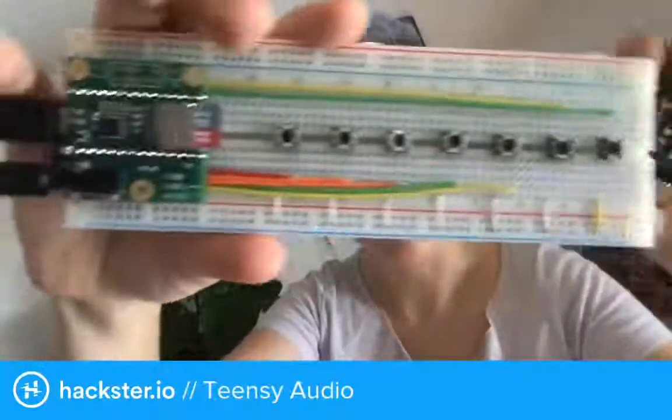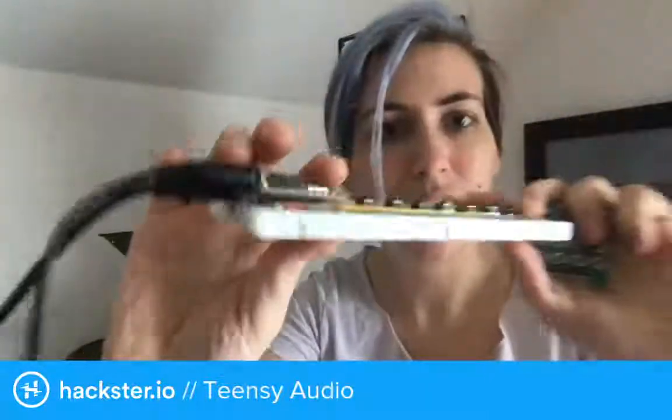Yeah, so here's the audio tutorial kit. You can see there's a Teensy underneath. I did a kind of janky thing where I accidentally soldered the Teensy too close to the board underneath because I only had one size of headers, and I was worried about heat problems, but that hasn't been an issue so far. The main problem is that I can no longer reach the reset button, which is back here. It's literally like 0.5 millimeter below the audio board, and so I had to instead solder on a new reset button, but that works too.